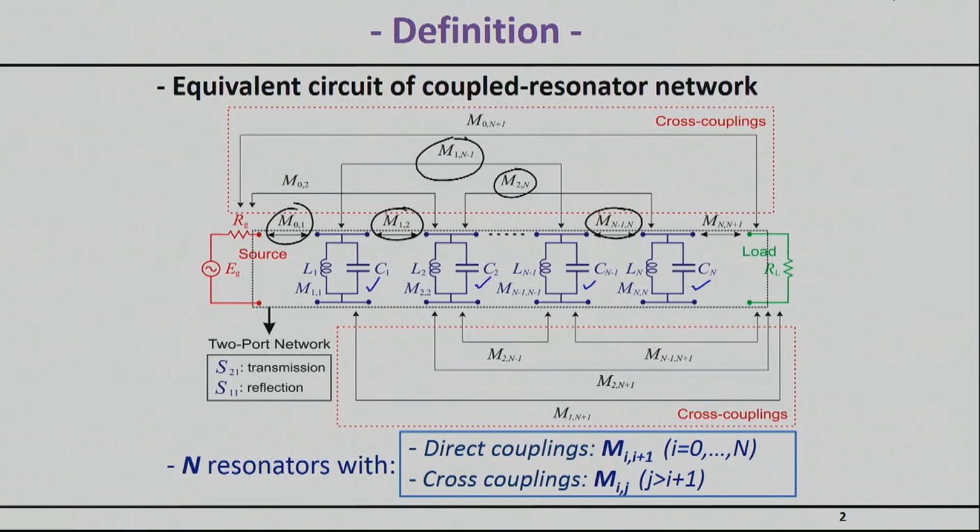But it's also important to realize that even if you don't intend to have a coupling section, parasitics may introduce one. A lot of times, people who lack this knowledge try to understand why, for example, an extra transmission zero or an extra pole exists. When you see something like this, it's almost certainly a parasitic coupling that you can actually get rid of. We also are going to assume that we have real loads, so a real load here and a real source here, and the rest of the things we've actually talked about before.